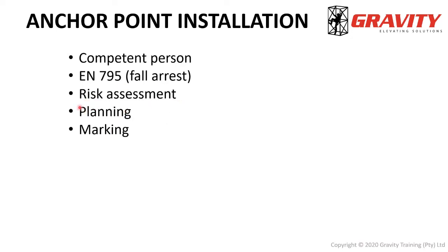The planning that we talked about now in terms of how many you use, how far apart you put them, what direction they will be used, will they be used for rope access, will they be used for full arrest. Make sure that you have that planning in place and that you involve a fall protection plan developer as well. They will be able to assist you with things like, if you put the anchor there, it may have a risk of a swing back or swing down, those kinds of issues, which again Johan Strauss went through in quite great detail in his masterclass.